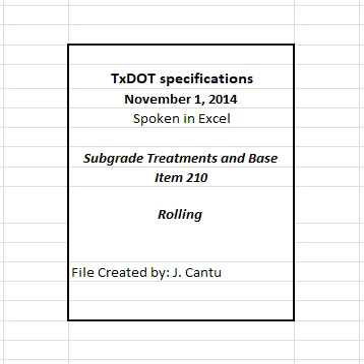Furnish a unit with at least 7 pneumatic tires, with an effective rolling width of approximately 7 feet. Capable of providing a total uniform load of 12 to 25 tons, and with tires capable of maintaining a minimum ground contact pressure of 80 psi or 90 psi as directed.